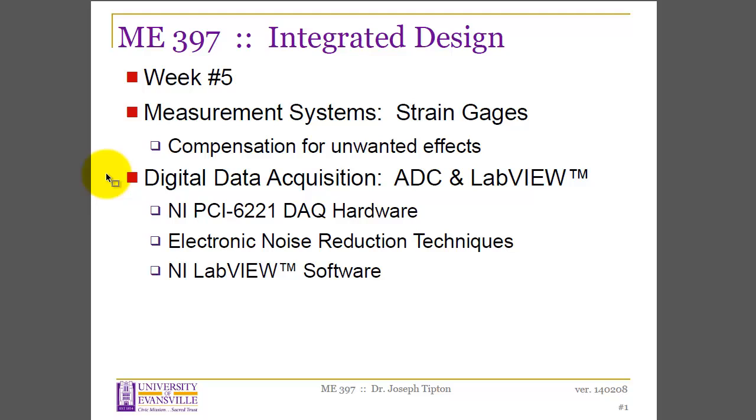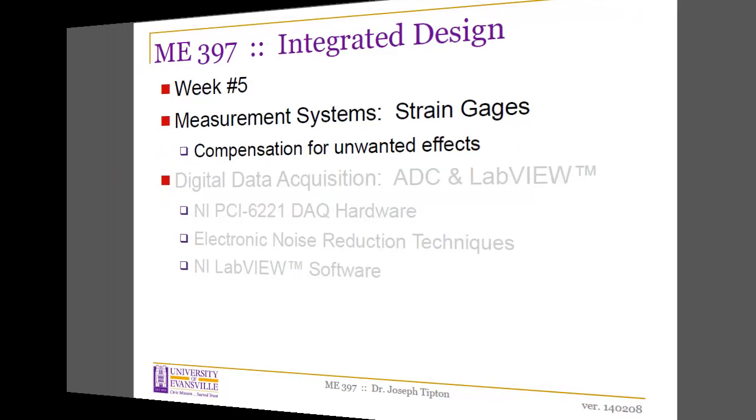We're doing this because your next assignment is going to involve creating your own Wheatstone bridge to measure a strain from a strain gauge, and you're going to measure that voltage using your LabVIEW program through your computer DAC system. So first, let's look at strain gauge systems.